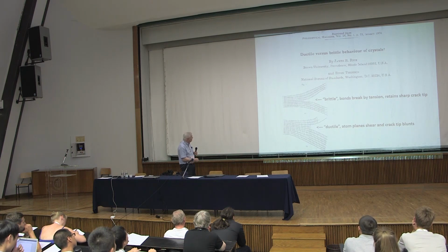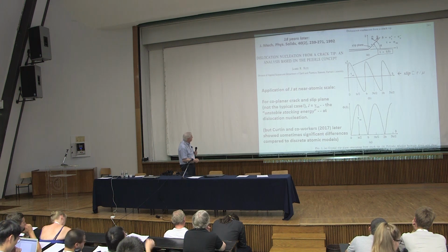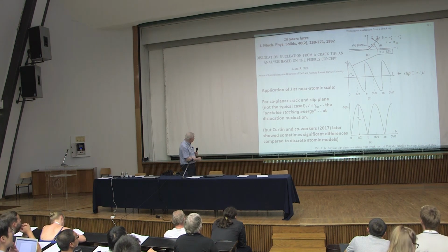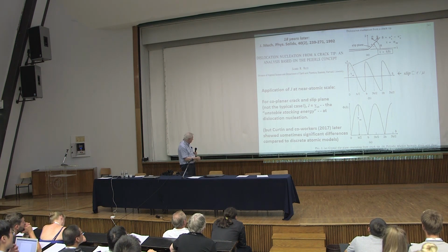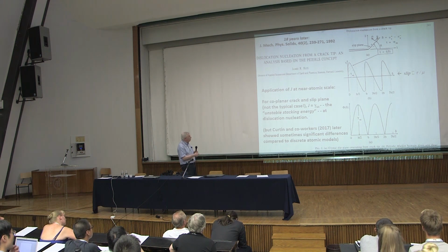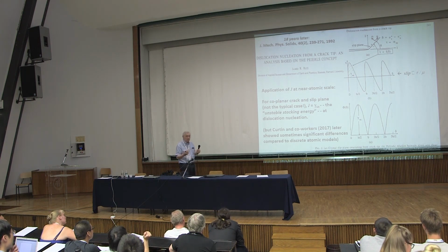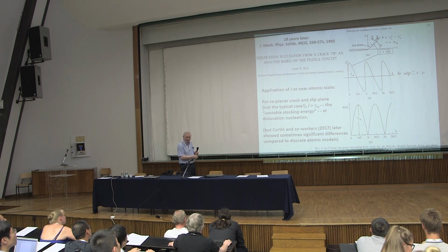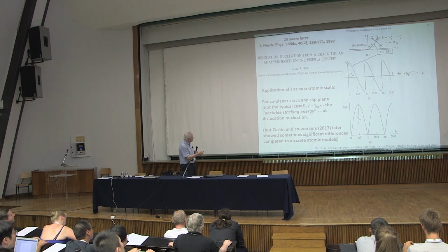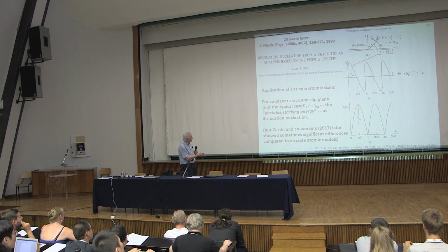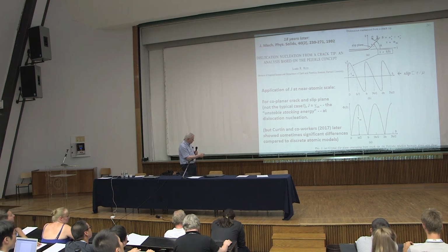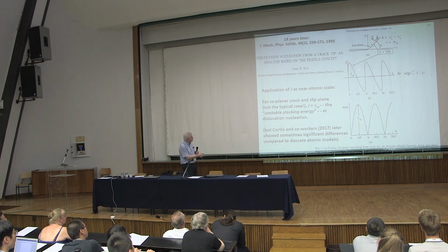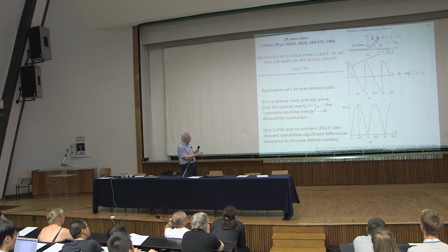So in using that, again, the J integral came into that. I tried to take that a little further, and I was happy with this work when it was done, but since it was done, Bill Curtin and his co-workers in Switzerland did direct atomic modeling. We tried to take an atomic scale phenomena and treat it by continuum theory, which means you're walking on shaky, rather tentative ground, and Bill Curtin showed that in some cases it was very shaky ground, nevertheless. But our simple continuum approach could look at a relation for shear stress versus separation distance and use that to estimate when the shearing near a crack tip would reach a point of instability so that you spit the dislocation out. So it would be the onset of the plastic yielding near a crack tip.